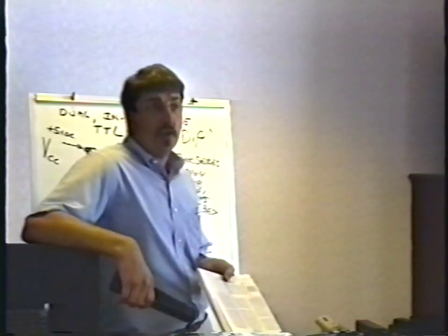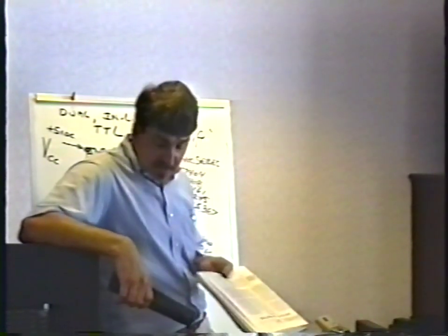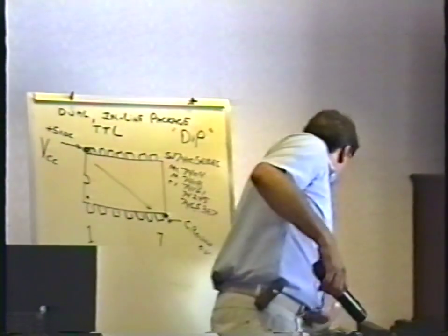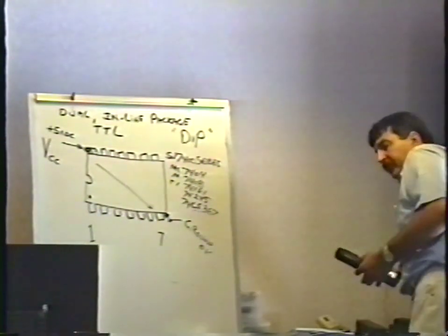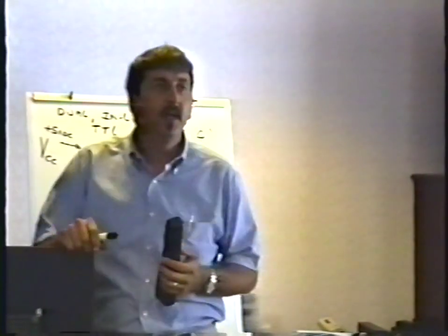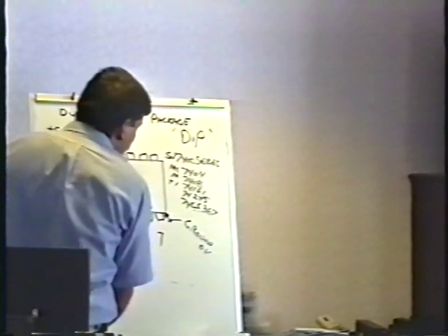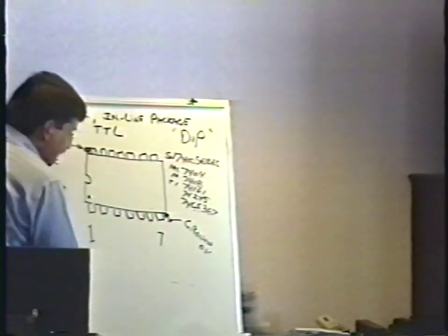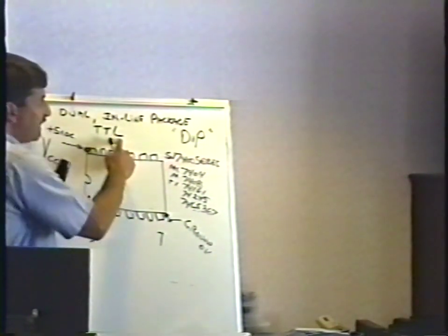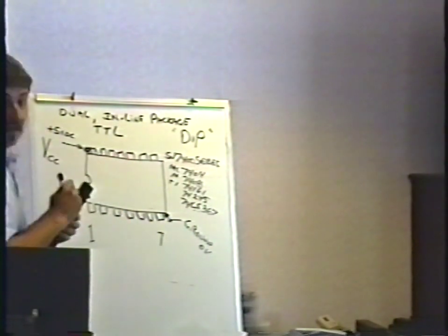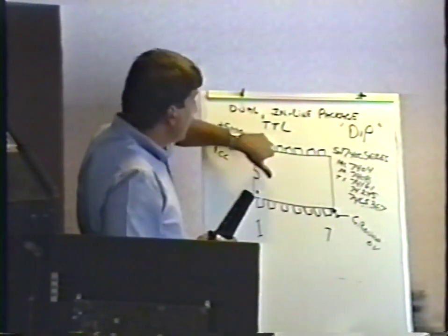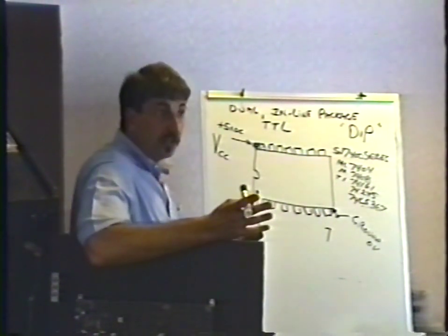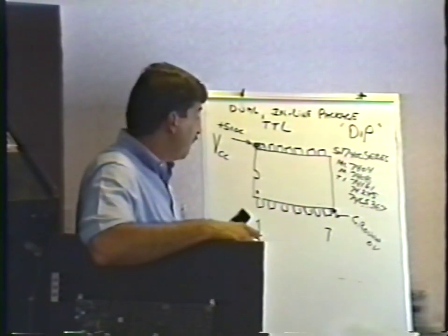What I'm about to show you is something that I'll discuss again when we talk about pinball machines. But it's a little trick that will enable you to find bad integrated circuits on logic boards without even knowing what the hell you're doing. And it's based on the fact that these integrated circuits are TTL, transistor-transistor logic. They're made of transistors inside. Remember when we tested the transistor, we were looking for that junction drop thing. Remember the junction drop, right?